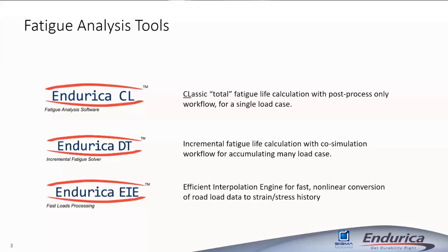Sometimes in rubber you have the combined effects of aging and fatigue, or cyclic softening and fatigue, and Endurica DT can couple with a finite element code, so that your finite element calculations can update the stress strain fields as part of the durability calculation. So it's a very powerful, flexible tool for incrementally defined problems. If you're using block cycle schedules, for example, in the automotive sector, you could use Endurica DT to model that.